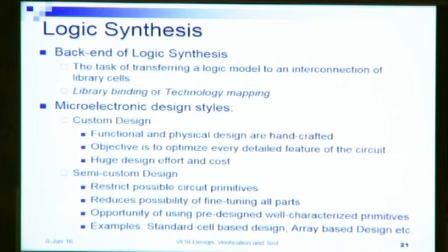Now, we said that in custom design we can optimize up to the last transistor, right? But in this you cannot do so. You have a set of pre-computed and designed unit cells of implementation, and that cannot be tweaked with by hand, and this restricts the number of choices that you have.